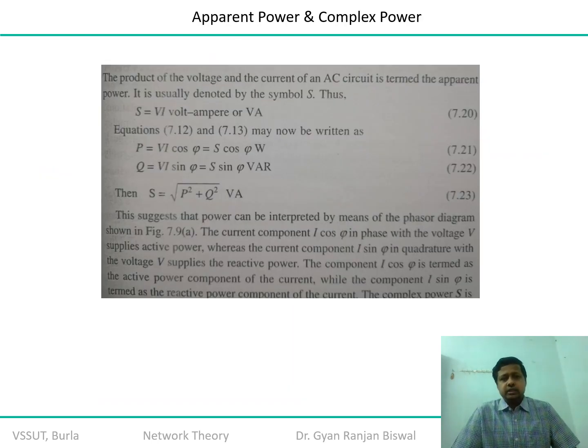Now, as far as the AC circuit is concerned, you know that there is a complex power, which is a cumulative complex conjugate response of the real and the reactive power. So for any AC circuit, to satisfy the 100% requirement of the product of voltage and current, we generally call it the apparent power, unlike the DC circuit. Remember, here your response is varied. So the complex power unit will be the volt ampere. This apparent power has two components: the real power and the reactive power.